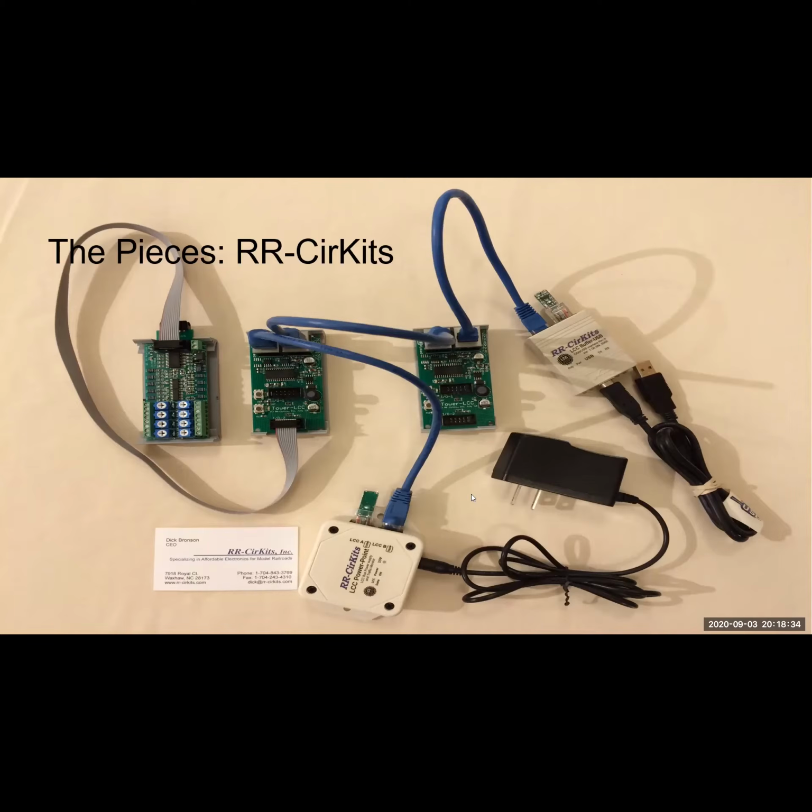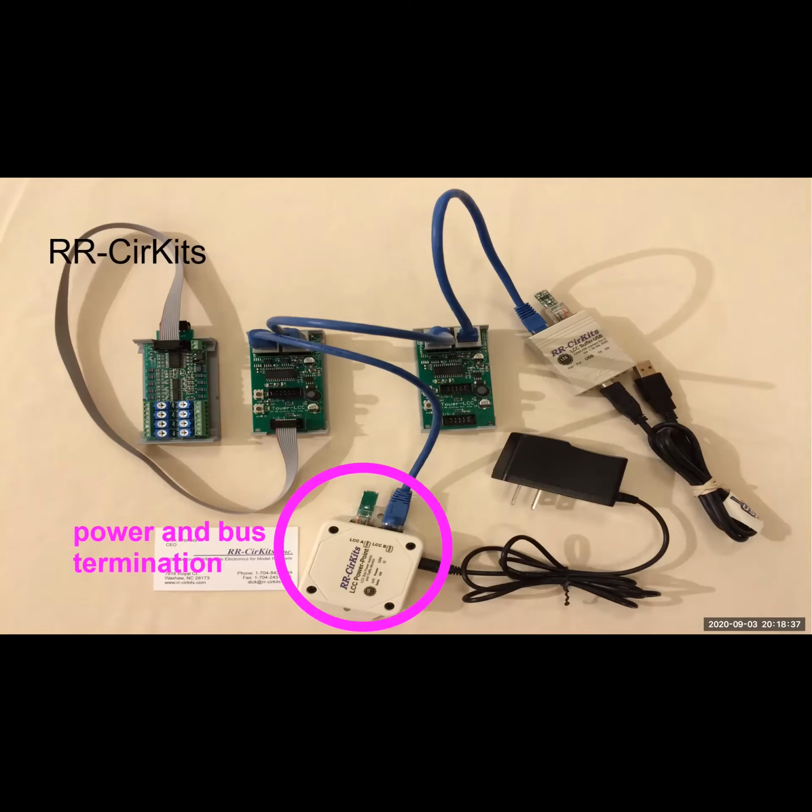All right, let's go through the components. I just want to show hardware first. First of all, there's this thing called an LCC power point. Basically, you have a power supply, a little wall wart kind of thing, and what it does is energize all the nodes around it. You don't need to send a power supply to all your different nodes. It injects power through standard Cat5 cables. You can get them at Micro Center, or order them off eBay or whatever. In the Cat5 cables, 1 or 2 pair, I don't remember, is a power bus that powers whatever it's connected to. So that's kind of neat. On the LCC group, we've agreed roughly 6 to 7 nodes off of 1 power point. So it kind of cleans up your wiring for one thing.